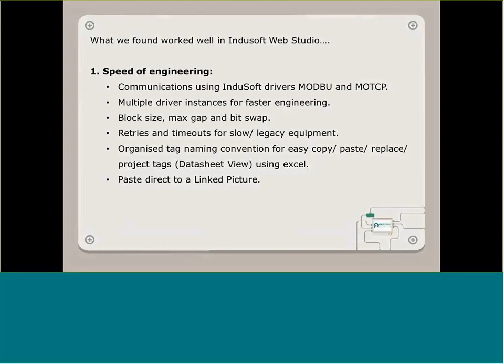Because we do so much Modbus integrating, we found that the Modbus drivers were fantastic. We found in a couple of instances for faster engineering that we could actually copy the Modbus drivers and use multiple instances of the same driver. We just found that using the main driver sheet is a lot quicker than having to use multiple sheets inside drivers. We could also do things like increase the block size when we knew a certain number of Modbus addresses could be read at once.